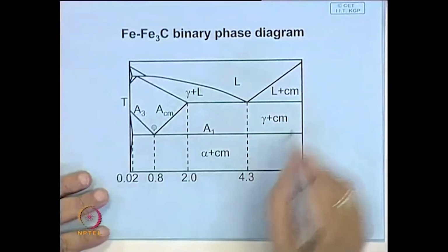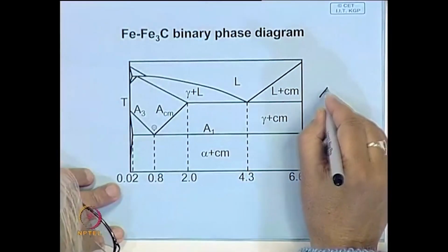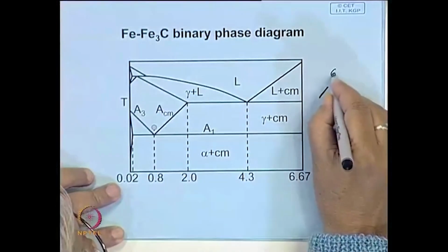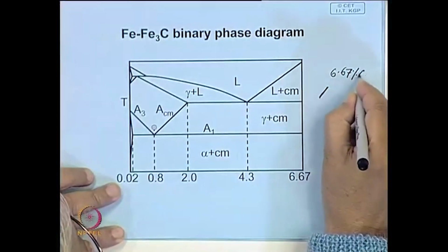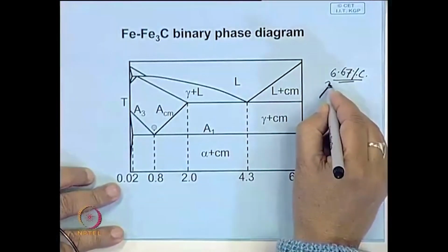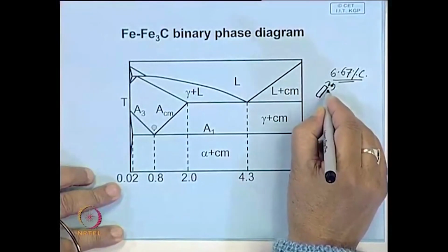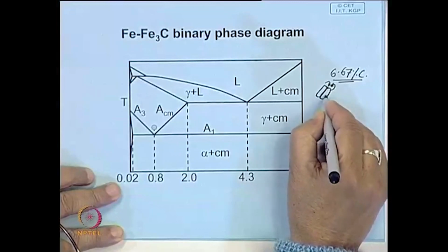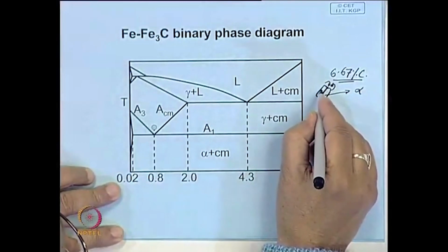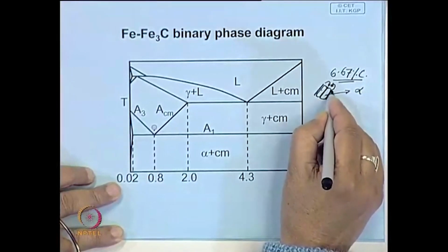And this pearlite, as has been mentioned, you have a cementite particle nucleating, a plate of cementite nucleates, it takes up 6.67% carbon. And where does this carbon come from? It will come from the surrounding region. If it comes from the surrounding region, the nearby region gets depleted of carbon and it forms ferrite.